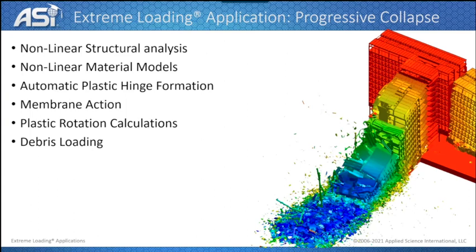In case you are familiar with the progressive collapse code, the new progressive collapse code, becoming effective by the end of this year, will allow some failure to happen in some locations inside the structure, but the engineer must take into consideration the effect of the debris loading. For example, if you are solving a case for a three-story building and you are removing a column from the last floor, then you have to consider the debris falling from the third floor onto the second floor as a loading scenario inside your analysis.